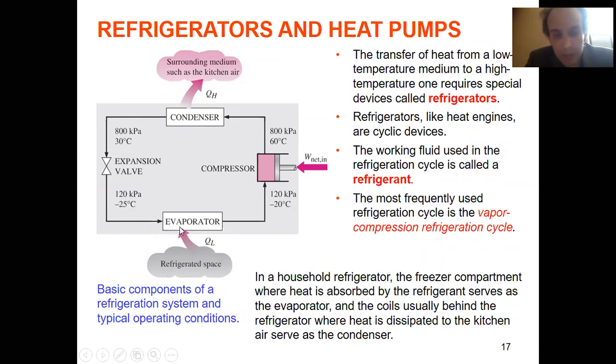And first of all, you have an evaporator. So what happens in the evaporator? In the evaporator, your substance evaporates, so it consumes latent energy from the environment when you evaporate, right? It becomes vapor. So here you take heat from your fridge, and then the task is to put it into your kitchen. How to do it? Here you have a compressor, and when you compress the substance, its enthalpy goes up, work is negative from your point of view, so enthalpy is higher, and then it condenses. What happens when it condenses? You release heat, and this heat goes into your kitchen, to the environment.